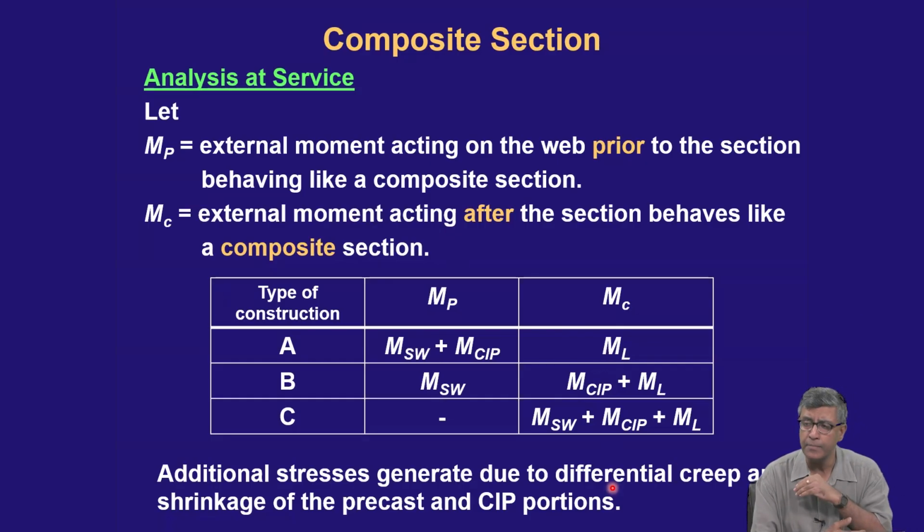For the ultimate limit state, typically you can say that I will consider the full section with the lower grade concrete. That is the easiest. As a student, I would say just go ahead and do that.